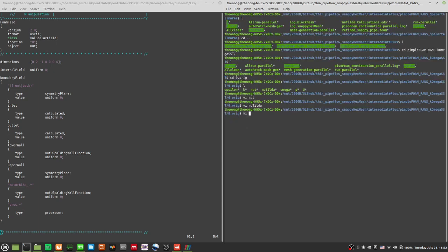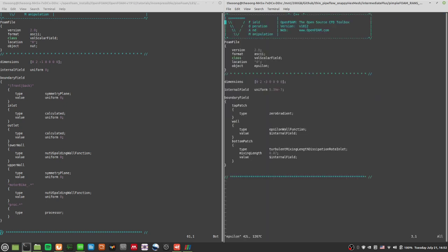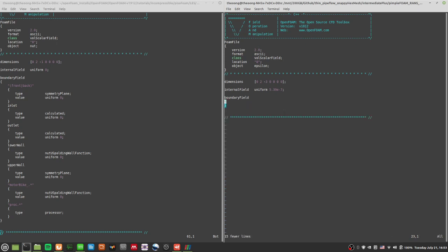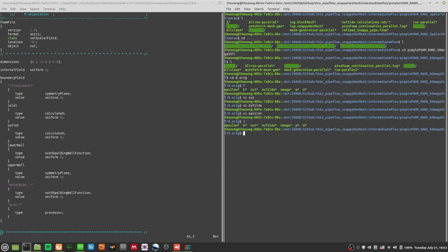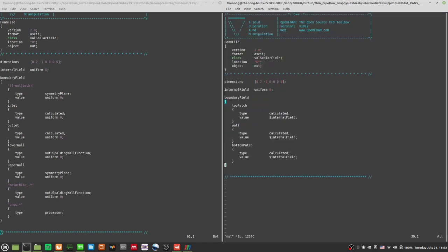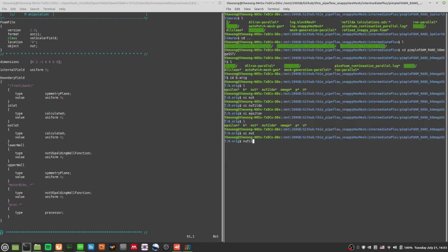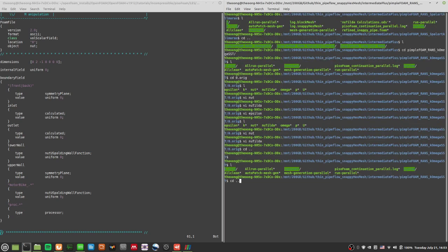Since this one uses k omega SST, epsilon will not be in use, so I can also delete this part. Maybe this one's 15 lines, dd. Just nice. So that's about it. nuT done, nuTilda done. Looks good, and this should be able to run.